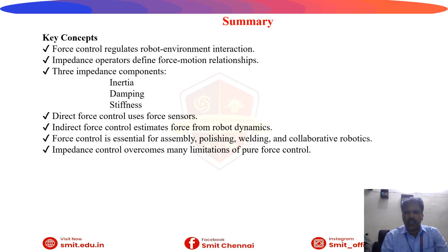Then the overall summary of today's lecture video. The main key concept: force control regulates robot-environment interaction. Impedance operators define force-motion relationships. Three impedance components we have seen: inertia, damping, stiffness.